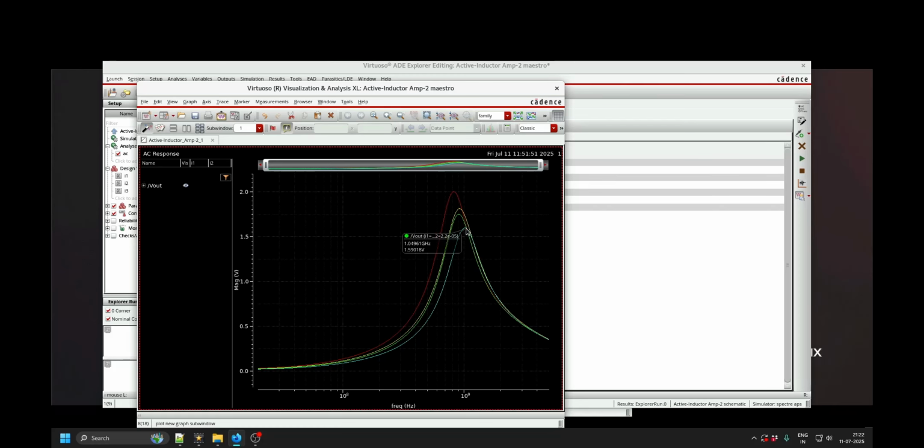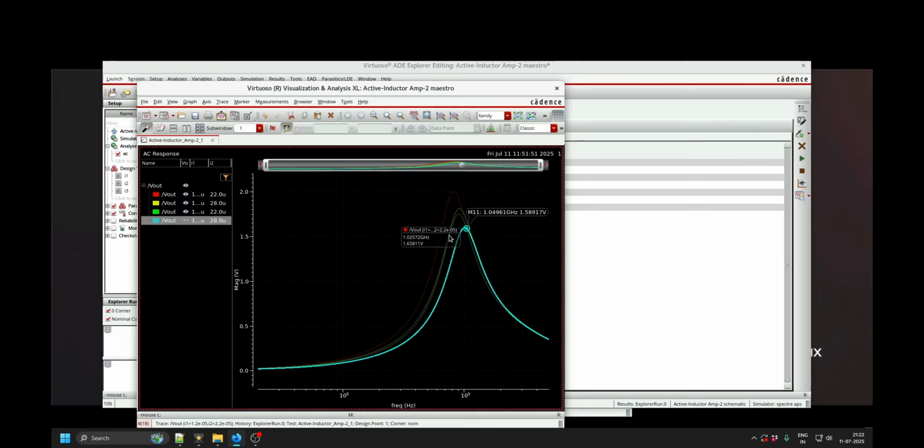So you can see here that it has reached 1 gigahertz, 1.014 gigahertz for this particular range. That's how you can select the values of I1 and I2 through simulations, by giving appropriate values and then finding the range. Depending on the range you want and how to tune within it, those I1 I2 values can be found using simulations.